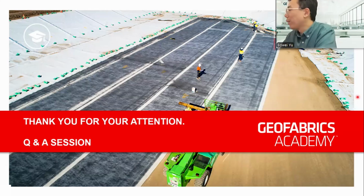Yeah, so this is the way we do it. But yes, our current equipment does have a limitation: the water level cannot go to the very top of the box, which means your top half box, maybe two-thirds of it, cannot be fully immersed in water. So if you want to test soil direct shear or aggregate direct shear, particularly in a consolidated drained condition, our equipment might not be the most suitable. So hope that answers your question.